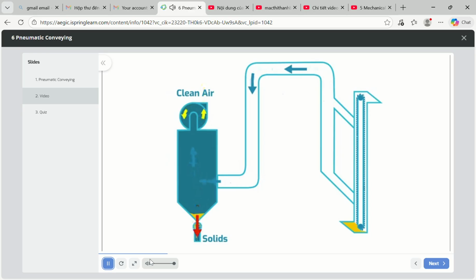The dust collector filters out solid dust particles from the airstream before exhausting the cleaned air to the atmosphere. In this example, the airspeed is controlled by the ducting diameter, the fan strength, and any baffles or valves within the ducting system that can create a partial barrier to the air current.